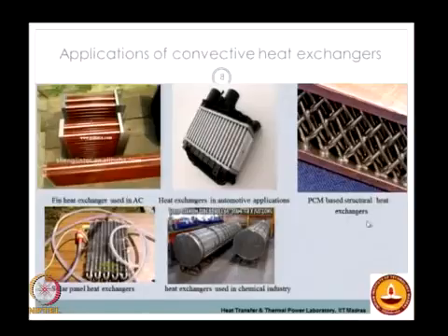heat exchanger here. You can also look at things like phase change material based heat exchangers, where essentially you have a cyclic process. In one half of the cycle you pass the hot fluid through a porous membrane which could melt upon heating, whereby it takes the latent heat of melting from the hot fluid and stores it as a capacitor.